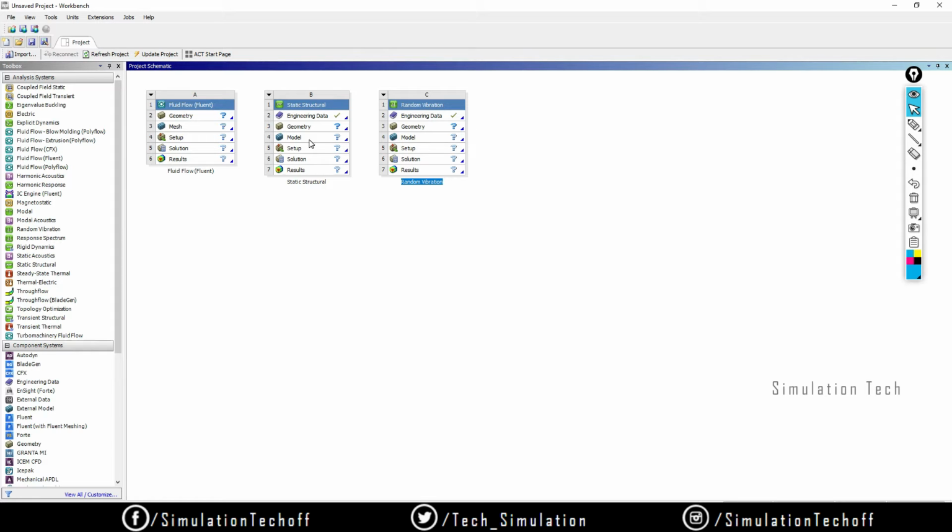Likewise, Fluent also has some steps. First you need to design the geometry, then create the boundary conditions, and assign the initial velocity and pressure, like this. Once we solve a simple problem, you will know, okay, I want to do this at the first stage and then move on to the next step. So you will get a pattern. Okay, so I will delete these systems, we don't need them anymore.